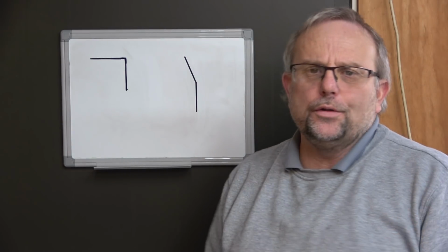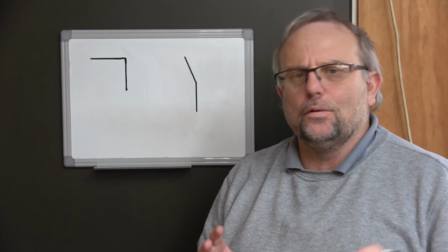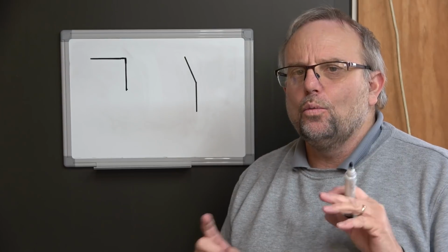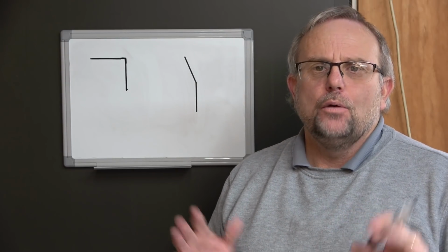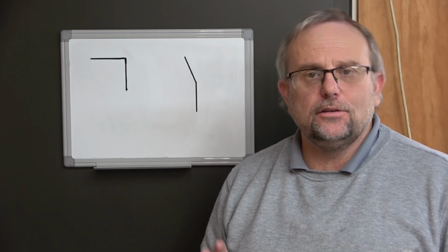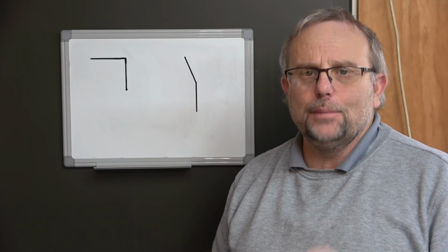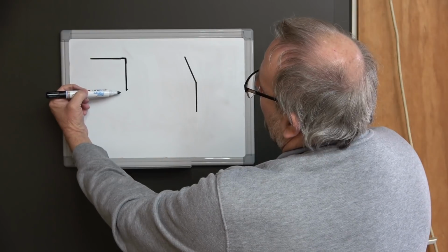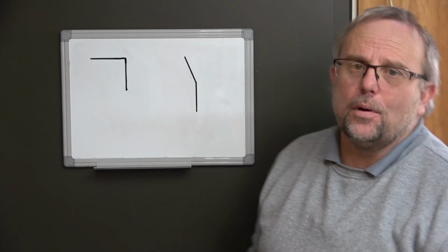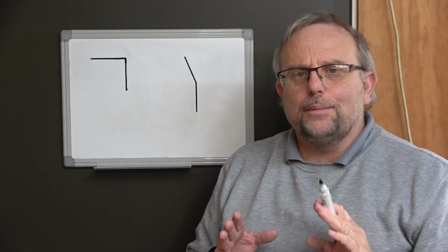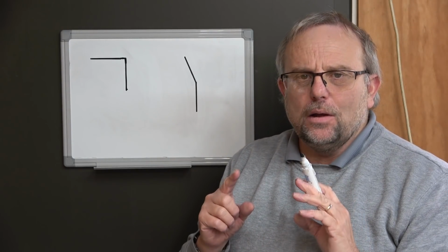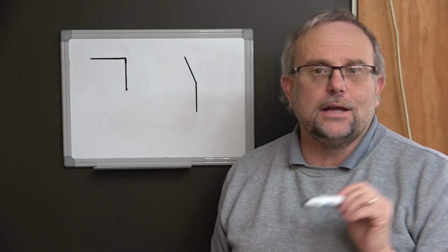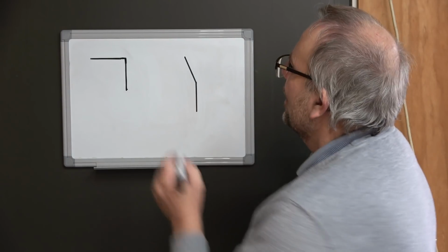So having gone to all the trouble of figuring out what that constant velocity distance tolerance is for my machine, what does it actually mean? Well, the 15 in my case is 15 units, 15 millimeters, because I'm running metric. But that doesn't mean I can come 15 millimeters away from my lines. What that means is from the end of the line, 15 millimeters before I get to the end of my line, I can start distorting the toolpath.